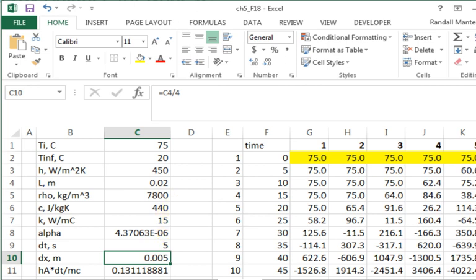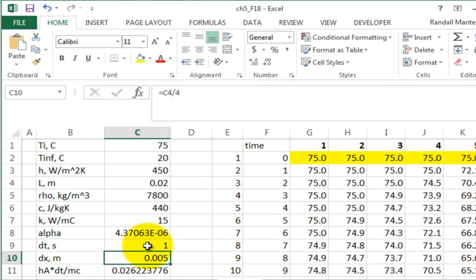So, has anybody ever experienced this in practice? Did you solve any problems and see that? Well, here you go. You see it where I coded it up, but it's nothing like coding it up yourself. When in doubt, cut your time step, cut your mesh size, increase the number of nodes and number of time steps, and then converge to a solution.